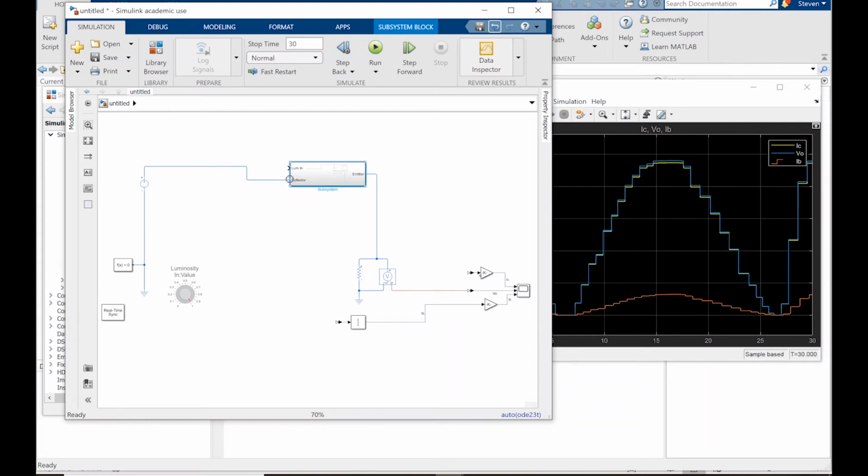I want it to look much more like an actual transistor schematic. So we've got the collector at the top, the emitter at the bottom, and the base at the left of the model. I'm resizing it. I'm basically just making my own electrical component. You can see in the box subsystem, it's a Simulink input arrow. I'm getting rid of a bunch of other stuff that I don't need. We've already modeled all the other values, so I'm just getting rid of that stuff.